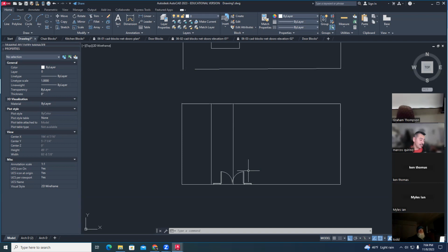If I brought all of those sinks in there, all the sinks would be in that project. And if I delete this and then go to insert, it's still there because I brought the block in once, it remembers it. Since it was a block, I can still insert it again from the block editor.